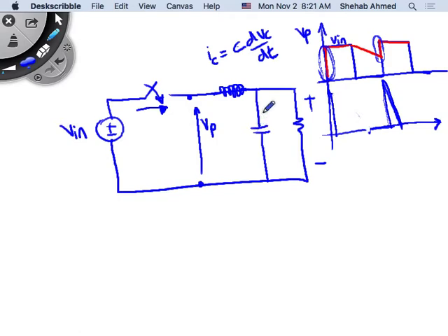like that. Capacitors don't mind if you charge them this fast, but then you have to rate them for very high currents. And then what else? Besides your switch being able to allow these high currents to pass through, your source also has to be able to provide this current. Batteries, for example, do not like to operate in that fashion. Batteries do not like you to draw a huge spike in current for a very short period of time and then stop. They do not like that.